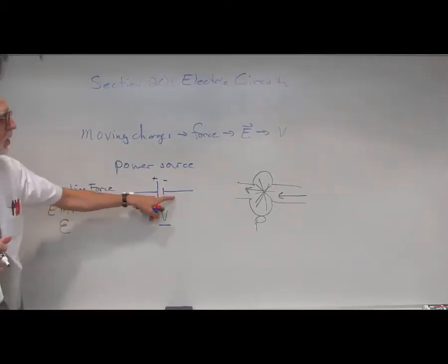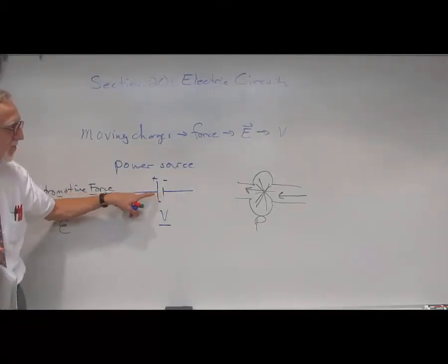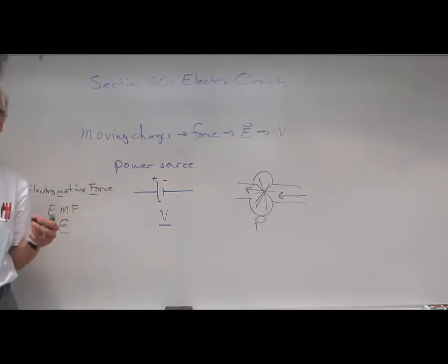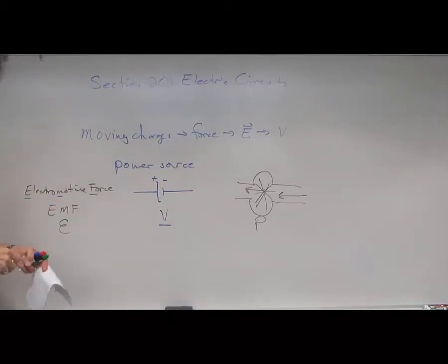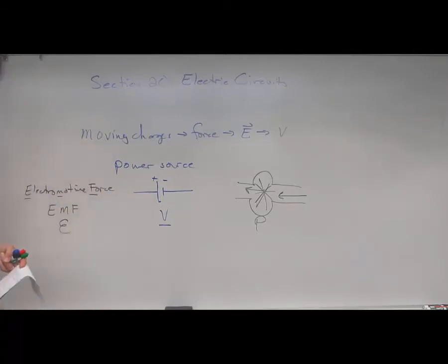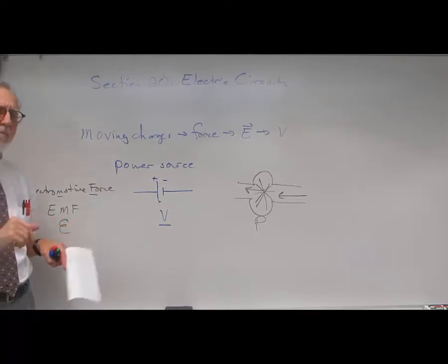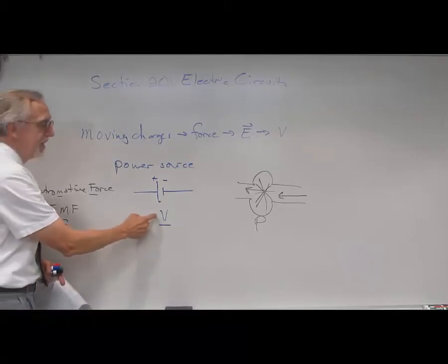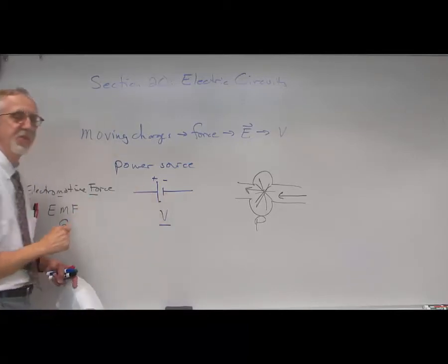The terminal voltage, actually the voltage at the ends of the battery, is a little bit different than the EMF. Batteries typically have what's called an internal resistance, and so the more current they are trying to put out, the lower the voltage. So when you have a load on the battery, it actually decreases the terminal voltage. But I'm afraid we're just not going to have time to worry about that, so we'll basically assume that the EMF of the battery is the same as the voltage at the terminals of the battery.